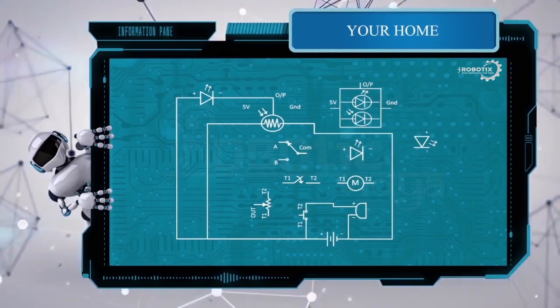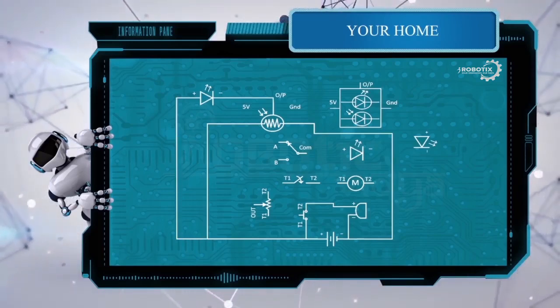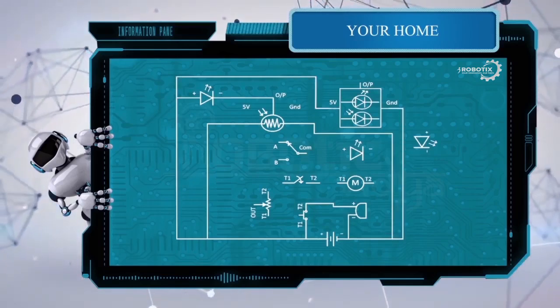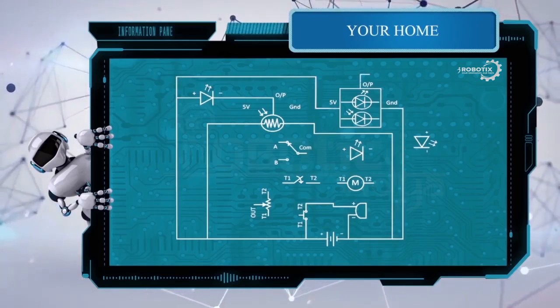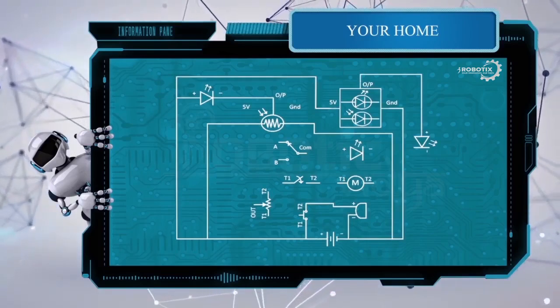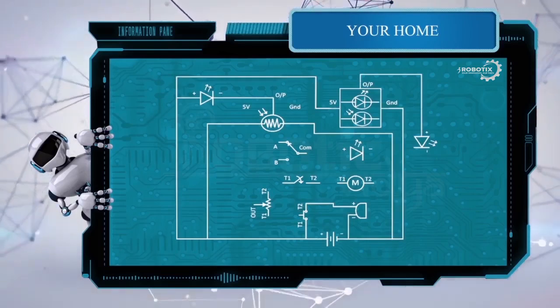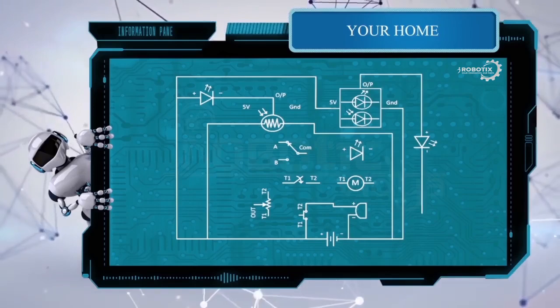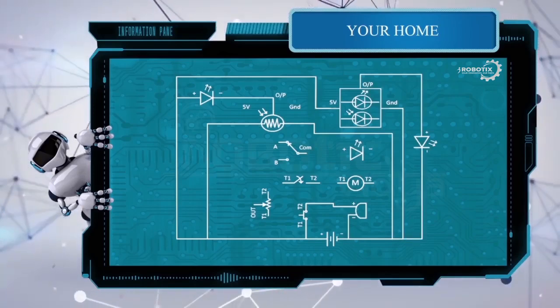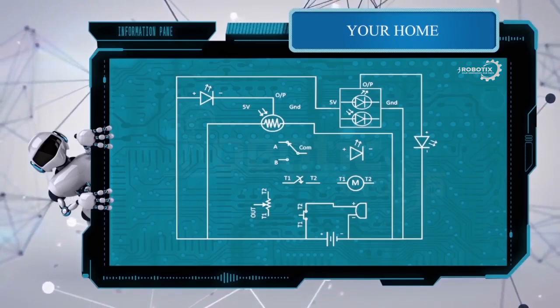The next is your infrared sensor. So again, give the plus and minus to your infrared sensor, and the output of your infrared sensor will be given to the positive of your LED and the negative of the LED will run back to the negative of your battery. The next is your switch and fan.